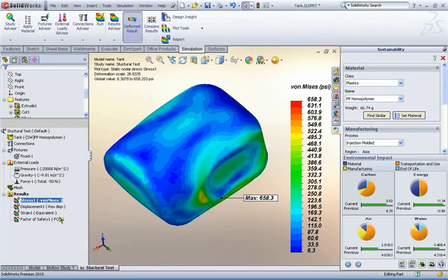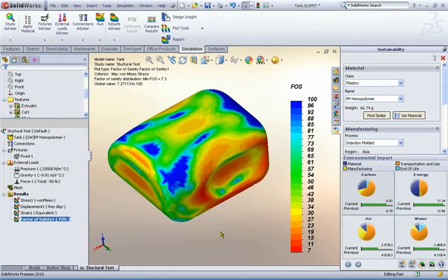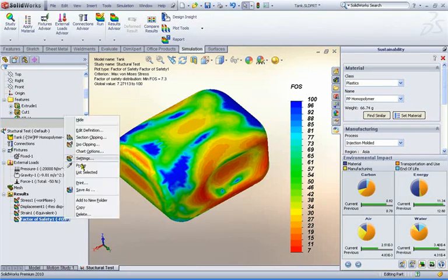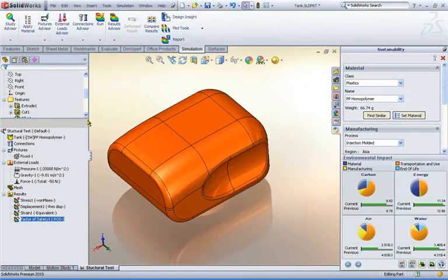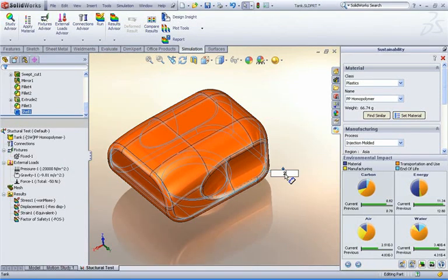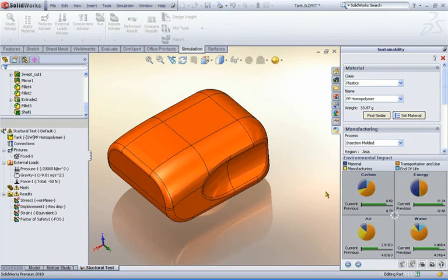The new factor of safety is about 7.0. It obviously has bumped up. But this is really cool because now we have a chance to trim our designs and remove some weight out of our designs. So let's say we change the wall thickness of this tank from the current value of 2 millimeters to about 1 millimeter. And watch, the dashboard in sustainability will automatically update based on the new volume as well.